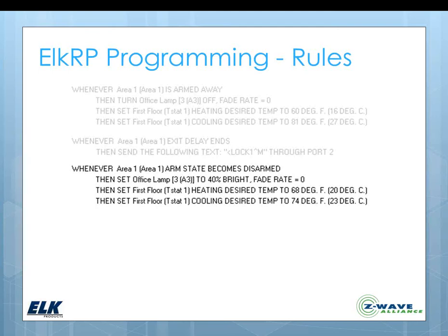We're also making some changes to the thermostats, and of course if we had multiple thermostats we could continue adding then statements to make changes to those thermostats. Now in these examples I'm showing changing set points. That's one thing that we can do. We can also change modes on the thermostat. If it's a type of thermostat that has auto heat cool, that kind of thing, we can support that, issuing those commands, and fan control and hold control are the basic things that we can do with the thermostat.